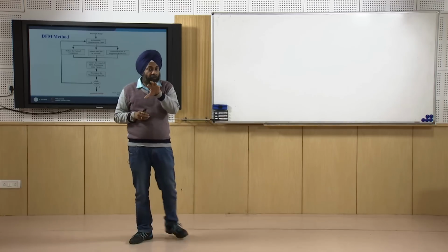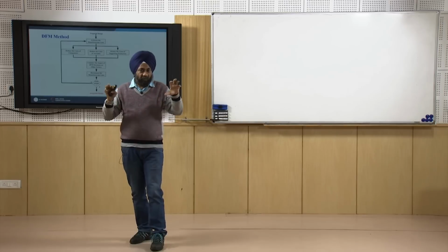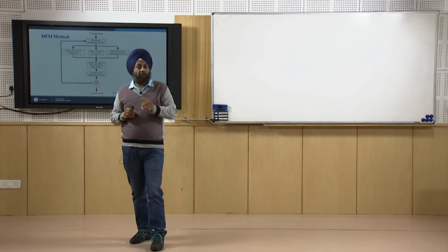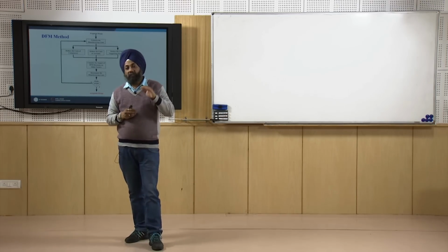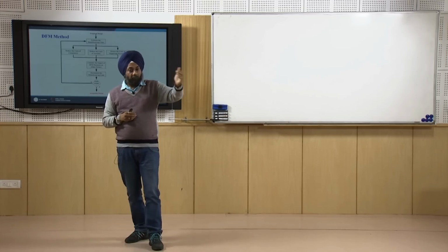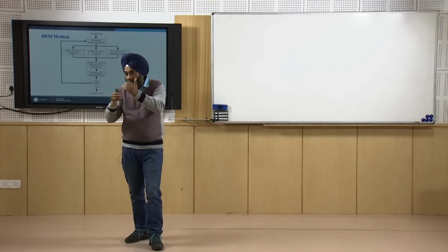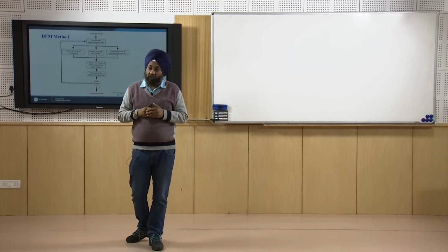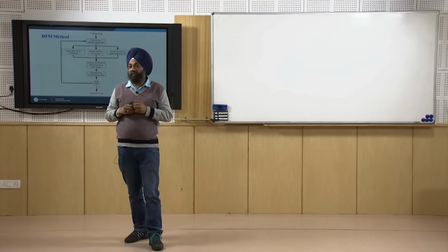analyze each and every product from the point of ease of manufacturing. We will try to reduce the costs wherever possible. Sometimes it may so happen that initially when we are proposing a change in the design, the cost may be slightly higher, but the process is faster so that it can produce more parts, so the overall production cost may become lower. So it is not always, maybe, when the cost is lower that we are achieving our target.